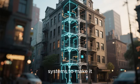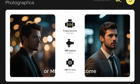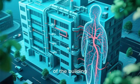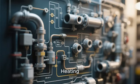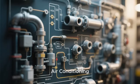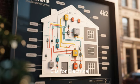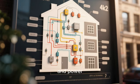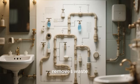A building is more than just a structural skeleton. It needs systems to make it livable. This is where the building services or MEP systems come in. These are the nervous and circulatory systems of the building. M stands for mechanical, HVAC, heating, ventilation, and air conditioning, which controls temperature and air quality. E is for electrical, which includes wiring, lighting, and power. P is for plumbing, which brings in fresh water and removes waste.